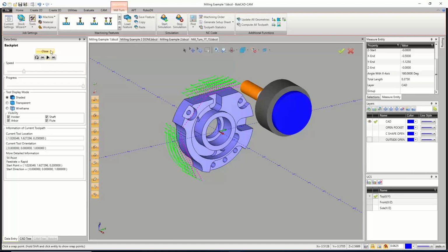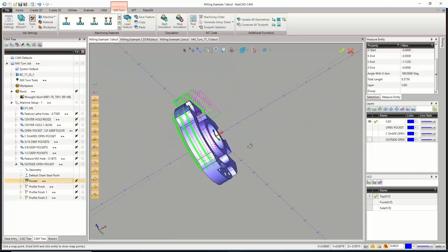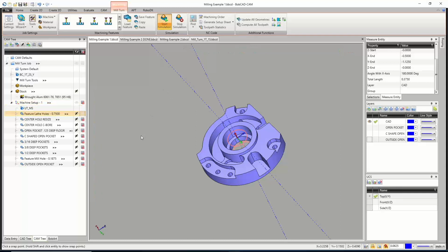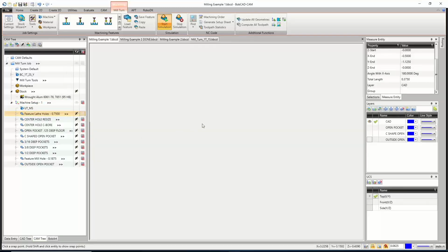And then we'll go ahead and close it. So yeah, I'll figure out what's going on with it during our lunch break here. I could start by going in and just pretty much turning off everything and then turning on one toolpath and seeing, does that one work? Yeah, no errors with that one. So it's just going through and kind of figuring out which one's causing the problem.